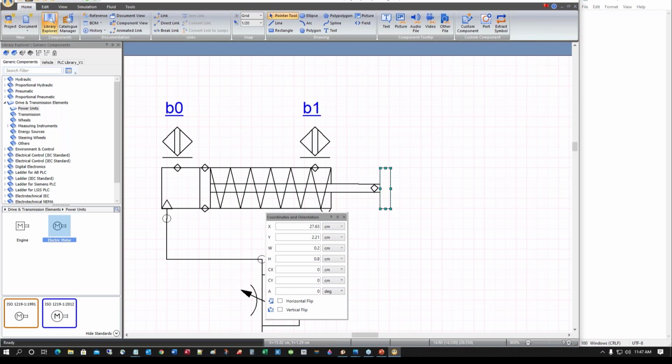So first of all, because of this snapping, I don't like it's 120. I want to snap to the grid. I want to see the grid where it is. For it to be aligned properly to the grid, the Y position, because I want to make it run straight on this line, is 2.2 centimeter. Now I want to make it in millimeter to make it more accurate, 278 millimeters. So I'm going to be working everything in millimeters.